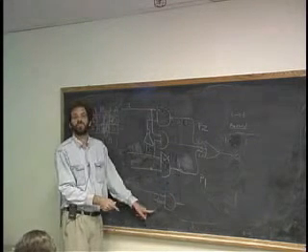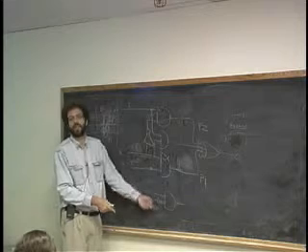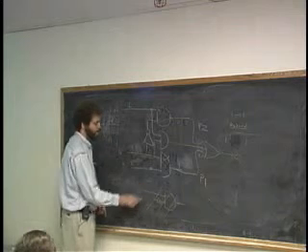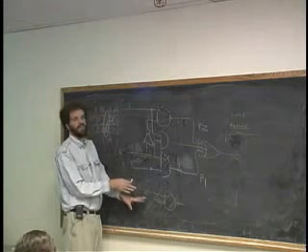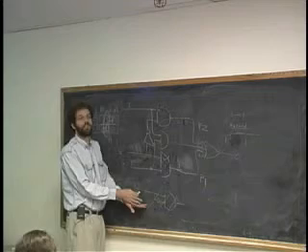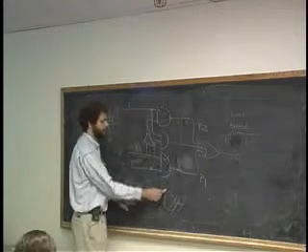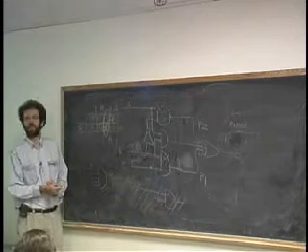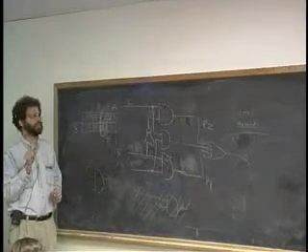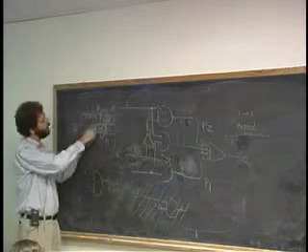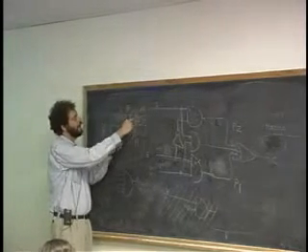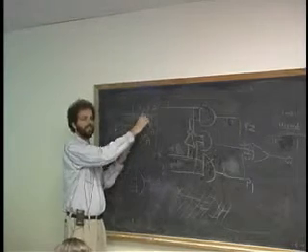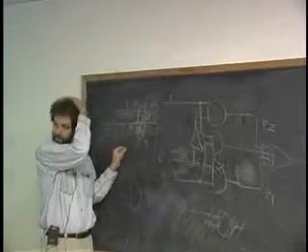However, would you ever want to do this? Does this ever make sense to put A and A bar? No. So this might generate a glitch. Technically, it is sum of products, but there'd be never a reason to do it. So for any practical sum of products logic circuit, you can never get a 0 to 0 hazard. Again, for single input change. And if you cover the path with AND terms so that there is never an interruption of these circles as you transit around, you can never get a 1 to 1 hazard.